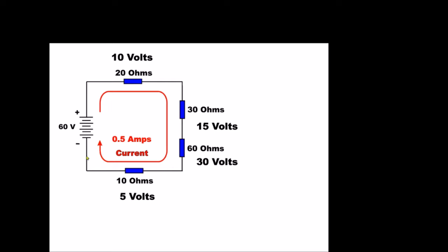We always measure from battery negative. While I have this circuit on here, you always want to reference to battery negative. Wherever you put your battery negative lead, you're saying is 0 volts, and anything you measure is going to be then positive. So let's take an example. If I put my negative lead on battery negative and measure this point here, which is basically right across the battery, I'm going to measure positive 60 volts.